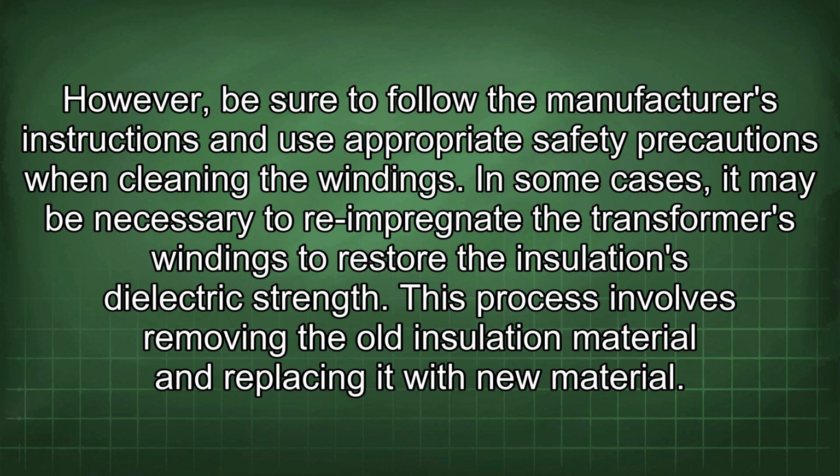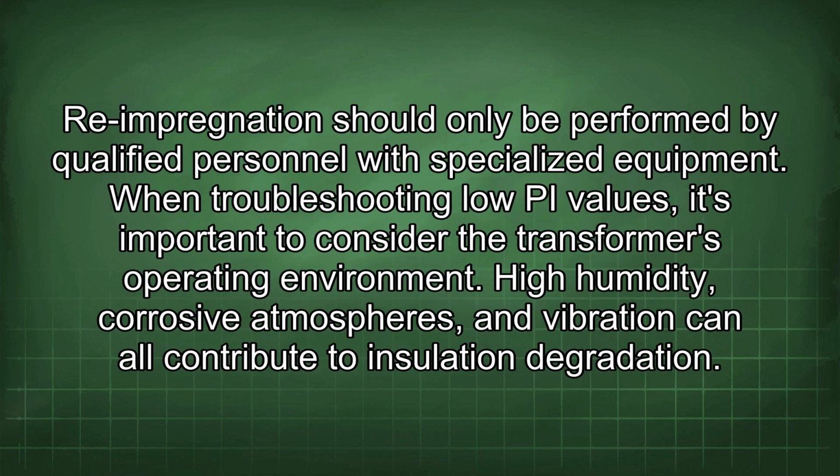In some cases, it may be necessary to re-impregnate the transformer's windings to restore the insulation's dielectric strength. This process involves removing the old insulation material and replacing it with new material. Re-impregnation should only be performed by qualified personnel with specialized equipment.